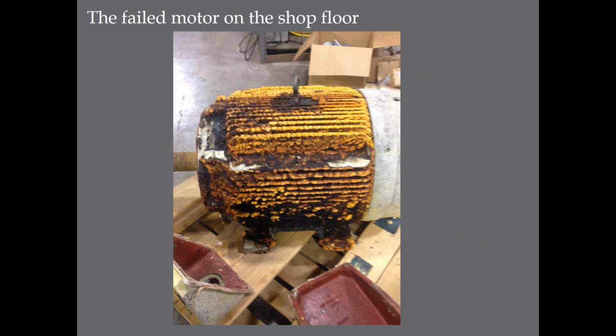This motor should have been clean. There was no way it was cooling. Yeah, the bearings are going to fail. Probably the windings would have failed if the bearings wouldn't. I don't know really what failed until they took it apart. But again, that's just a general comment. It locked up. That's not why the motor failed. Some component in that electric motor failed. And I can tell you a couple reasons why it would have.